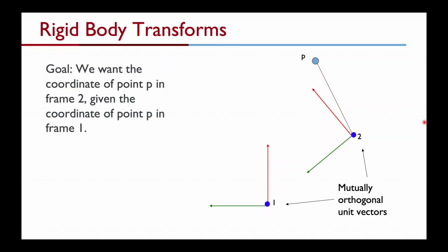And this is a good transition into rigid body transformations. Okay, so I've said this before that we are treating our car as a rigid body, meaning that it's not made out of jello. So there are some coordinate frames between which the transformation is always static. Right, so the distance between the LiDAR and the rear axle doesn't change. It may change slightly because the suspension of the car actually bends and tilts at high speeds, but for the most part, you can treat it as a rigid body.